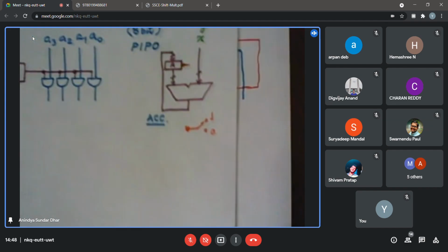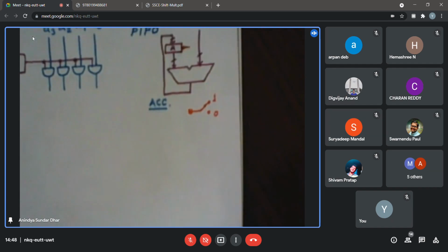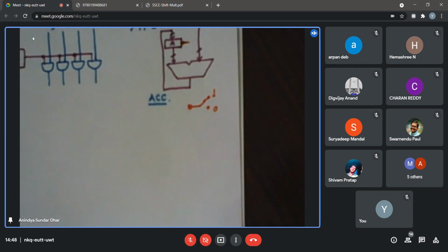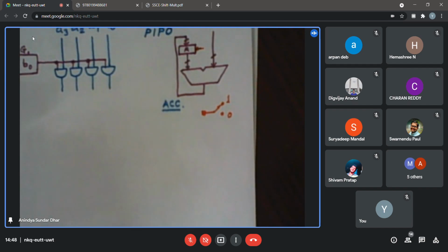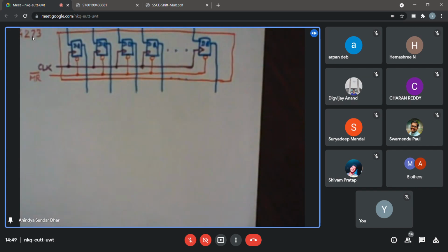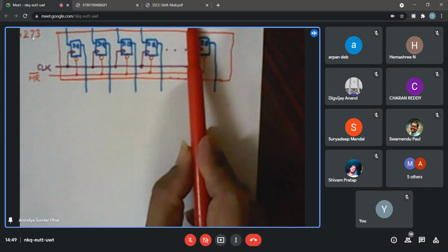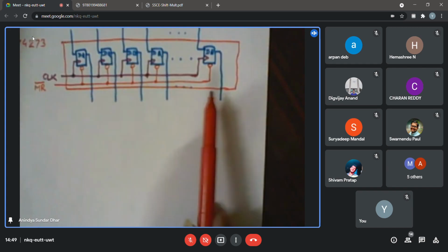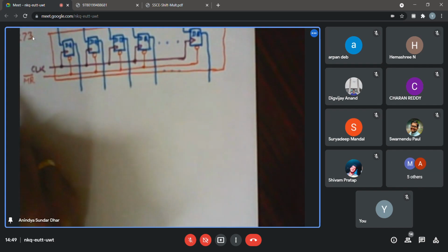So right now, I think you can use such a manual resetting operation. Then I may ask you to automate that one also probably. So anyway, now coming back to whatever we have been discussing about 74273. That is called parallel in, parallel out, because in parallel you can put 8-bit numbers and you can get parallel output of such things.